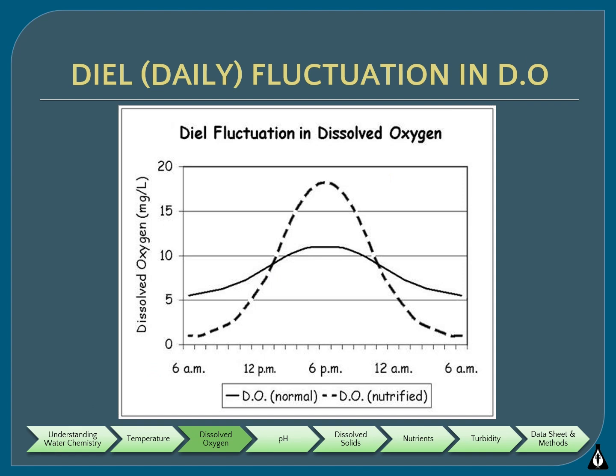If the previously mentioned factors result in a large dip in dissolved oxygen at night, you might have problems first thing in the morning. You can see on the graph where the dissolved oxygen levels at 6 a.m. are below 5 milligrams per liter and within lethal limits for aquatic life. In other words, organisms that require oxygen could begin to die if the dissolved oxygen drops below 5 milligrams per liter in a stream. This is especially true if the night is followed by a cloudy day. This is why water quality professionals try to take dissolved oxygen readings early in the morning so that they can potentially see this increased swing in dissolved oxygen throughout the day.